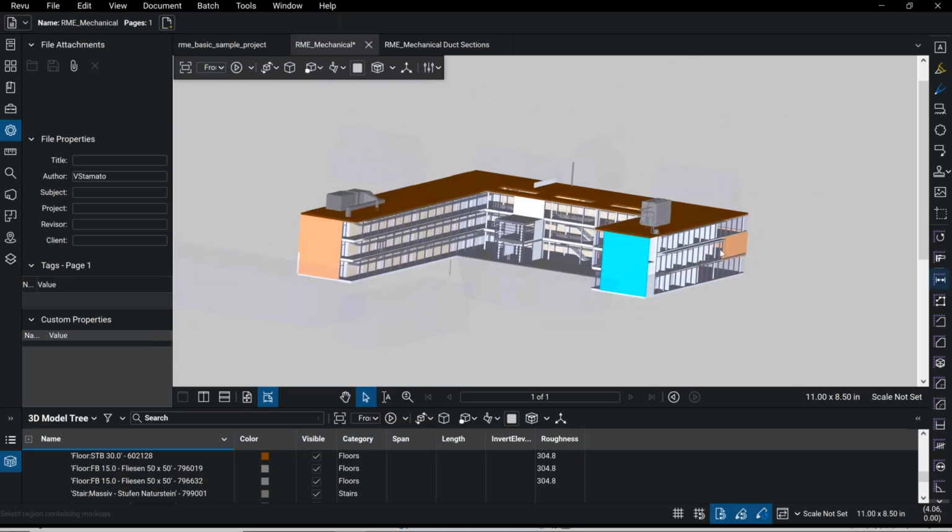All right, folks. So next thing I want to do is I just want to take a peek at my notes here, make sure I'm getting everything covered that I'd like to take. So we're looking at basically the IFC file. When you create an IFC file from Revit, it's going to give you the entire 3D model. You're not going to be able to separate the model into little pieces. What I want to show you next is how to create a 3D PDF of a cropped down view from Revit.